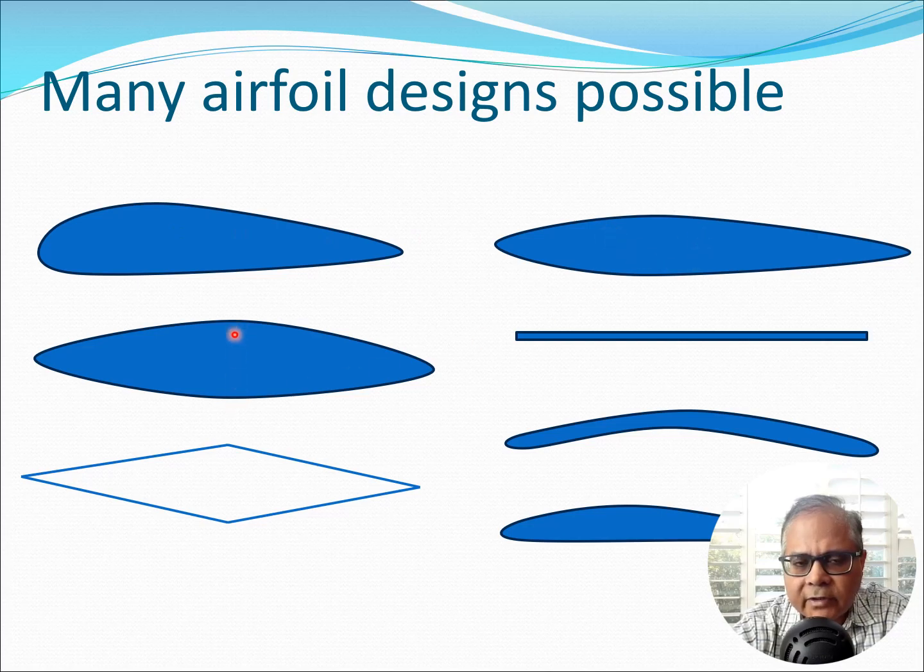The laminar airfoil sections were not very successful for laminar flow because, as I mentioned before, often the flow would separate, but they are actually good for high speed flow and supersonic flow. So in supersonic flow, we sometimes have a wedge type of airfoil section, or we can also use something like a laminar section there. Also, there is the possibility of using something as simple as a flat plate as an airfoil, typically at lower Reynolds number.